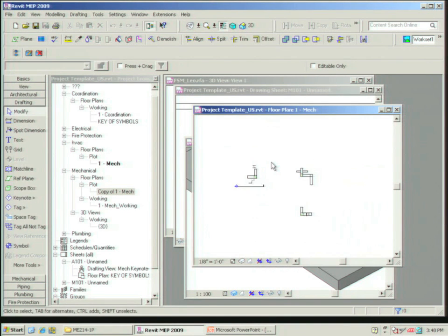And the one last thing is, let's say you linked your architectural model. As soon as you link that architectural or structural model, by default, you're going to have a gray background with a default architectural background, which you don't want to see. It doesn't even have room names. It looks totally different than what you see in a printed out architecture drawing. Even the architect has 10 different types of plans in one floor. And they're using the same technique, well, a little different technique, to create the same plan views in their own architecture drawing.